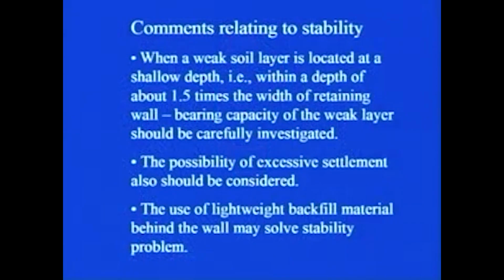Now, this was all about the stability of the wall. There are a few points or comments that we must know about the stability of the walls. So let us discuss one by one what those comments are. When the weak soil layer is located at a shallow depth, that is within a depth of about 1.5 times the width of the retaining wall, the bearing capacity of the weak layer should be carefully investigated. Wherever there is a presence of any weak soil layer, we need to be extra careful. That is what this first comment tells us.